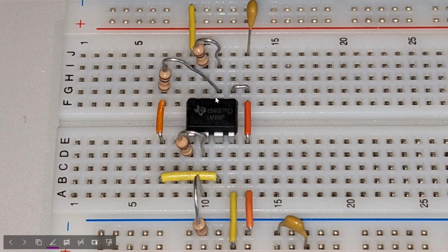In fact, if you watch that video, you'll notice that the upper part is unchanged. So this is the inverting amplifier with that 100K feedback resistor as RF and this 10K as RIn. To that, we've added two more resistors, and that allows this side here to be the non-inverting. There's a 100K resistor here, that's RF for that particular op-amp, and then a 10K resistor here.